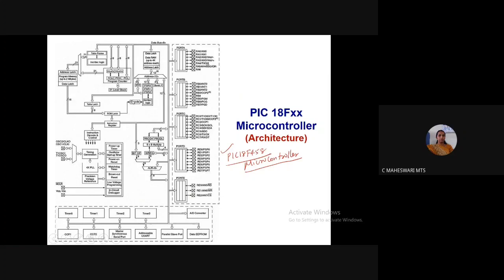Here this block represents the data bus. Through the data bus you have data RAM, that is 4 KB of data RAM maximum. The address for data RAM is 12 bits and data is 8 bits. 12 bits is to access 4 KB of memory.